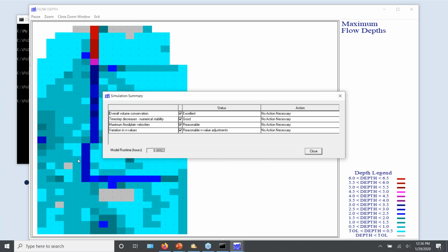So my point of this is that adding the rainfall to this alluvial fan simulation has two values. One is that it accurately ties the timing of the rainfall and the mud flow for the overall event, and it dilutes the mud flow as it moves. So you have to delineate whether or not you're going to have mud flow from rainfall only in the upper basin or as a landslide, or the storm is big enough that it may be more or less centered over the watershed, but it's also occurring on the alluvial fan.